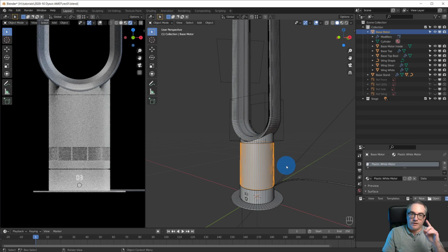Now, one thing to note here, we have a lot of modifiers, we have a lot of geometry, we have the exact Boolean modifiers, which are kind of slow. And for each frame that Blender has to render, even in the viewport here, it has to do all of this modifier magic. And that slows it down quite a bit. So this non-destructive workflow is a good way to build up stuff.